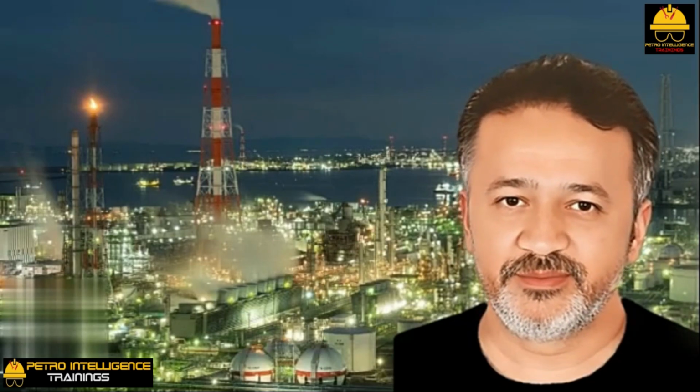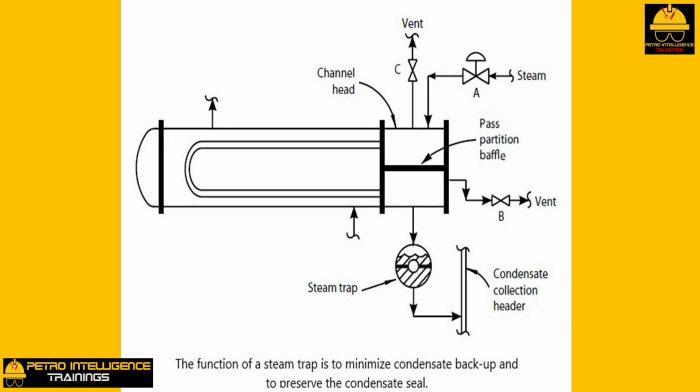Non-condensable venting. There is always a small amount of CO2 in steam. It originates from residual carbonates in the BFW. Compared to steam, the CO2 is a non-condensable with a limited solubility in H2O. As the steam condenses, the few ppm of CO2 will be trapped on the steam side of the tube bundle